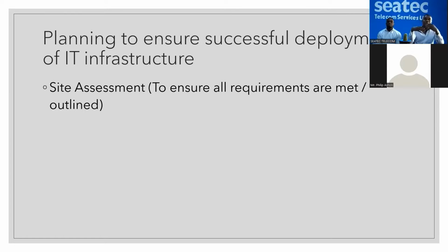So all these things require that upon the order, you go to site and ascertain the actuals on the ground. Have all the dependencies been met? Where you asked them to put tiles, are there several rooms being tiled? Is there supposed to be a raised floor, and has it been done? Is there supposed to be conduit piping, and have all those things been put in place? All these things inform your planning. It makes you know that you are not carrying things to go and wait. There are times where projects are outside Accra. You can't fly or sit in a car all the way just to realize something was done wrong. So it's important to go and look at the sites, have a visual view, know what is actually on the ground, and feed that into your drafted plan.